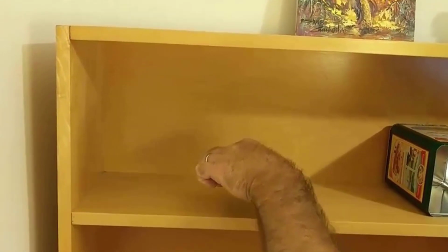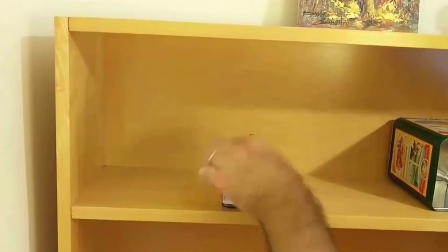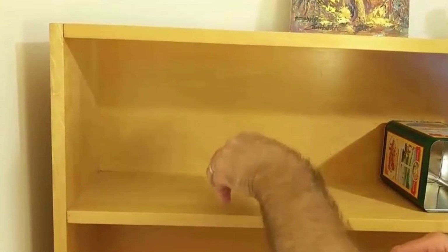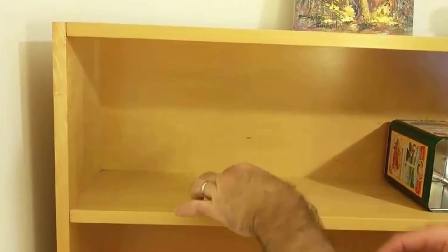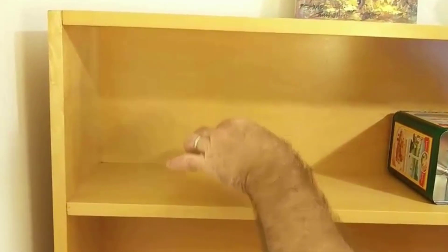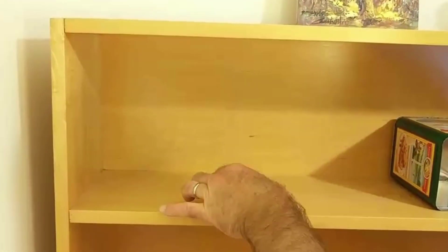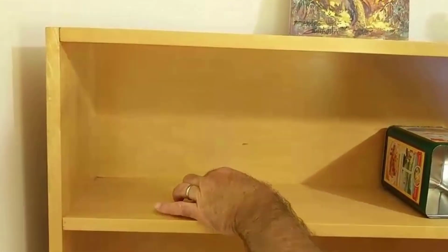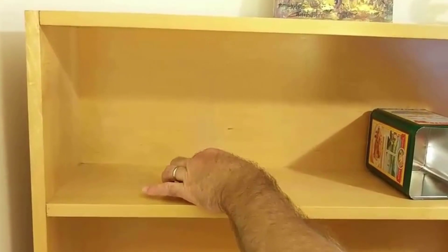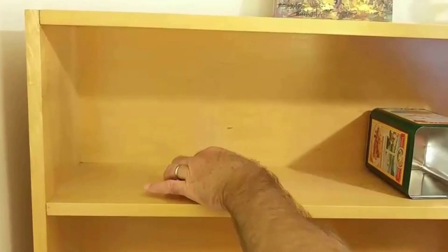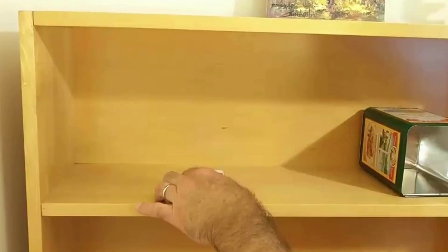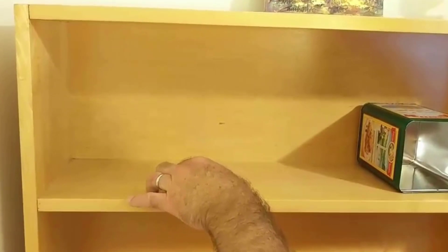As I get close to a wall, a hard wall, you can hear that that gets louder because the sound's reflecting and basically doubling the amount of sound emanating. So if you do the math, the decibel level goes up by 3. If you go close to 2 walls, you can hear it get even louder. 1 wall, 2 walls. That's a directivity factor of 4, which is a dB level increased by 6.